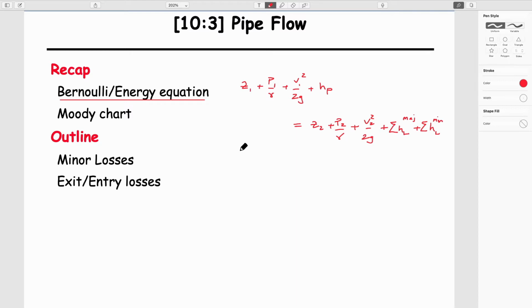Today we'll talk about these minor losses. We've already talked about pipe flow, and then we'll do some examples. I think we'll get far enough along to do that, and we can define all of these individual components. So the pump head is equal to W, unfortunately defined since we've used it for velocity, the power, divided by the mass flow rate, rho Q, multiplied by g, gravitational acceleration, always the case.